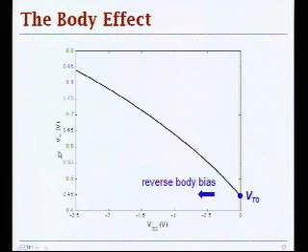You have your threshold voltage, and then you have bulk to source terminal. If you go into negative direction and decrease the voltage of your bulk relative to the source, then your threshold voltage increases as described in that previous relationship that we had, and that's a reverse body bias. You can see that starting from 0.45, you can increase your threshold by quite a bit.